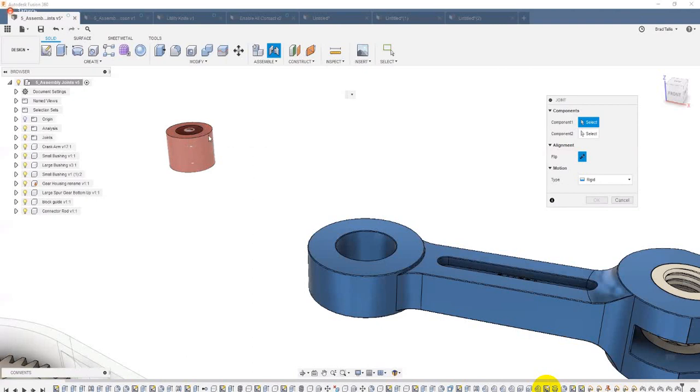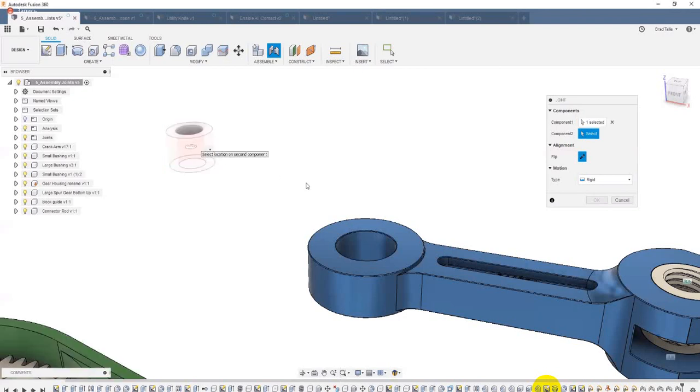You'll notice it's no longer looking for edges or other faces or anything like that. As soon as I let go of my control key, I'm back to here, okay? So all I have to do is get near a cylindrical face, hold down my control key, and it's no longer trying to catch to all those other edges and faces. So now I can basically just move up and down and grab that middle guy.